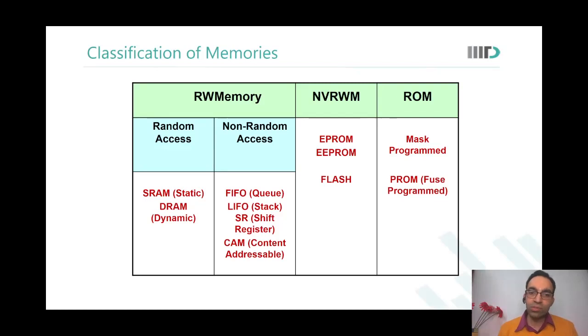Are you able to see this? So this is content addressable memory. I do not have the address location which I want to read. I do not even know about it. But I know the content that I want to match. So I give that match content over there, and for all the locations for which this content is matched, a read operation is initiated. Is that okay?